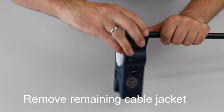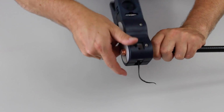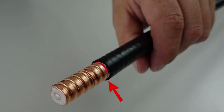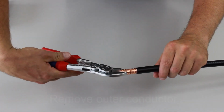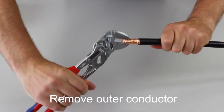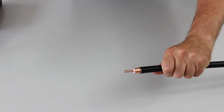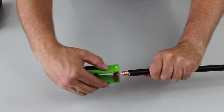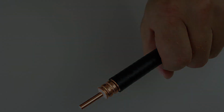Using the peel insert on the Uniprep tool, peel the cable sheath back to the previously formed sheath cut by turning it around the cable and then remove any residues. Using the pliers, pull and twist slightly at the same time to detach the outer conductor from the inner conductor. If there are any dielectric or plastic residues, use the cable stripper to remove them without scratching the conductor.